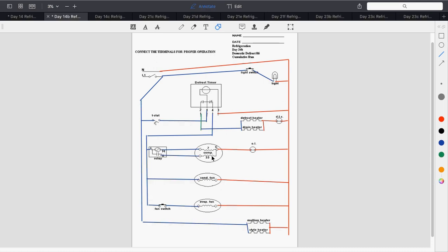Okay, that will energize the magnetic field enough to close that normally open contact and energize the start winding. When the motor starts running, the current drops way down, and it's going to de-energize that relay, and the normally open contacts go back to open. It's the only one that you'll have in series with the run winding of a compressor motor. So just be aware of that.